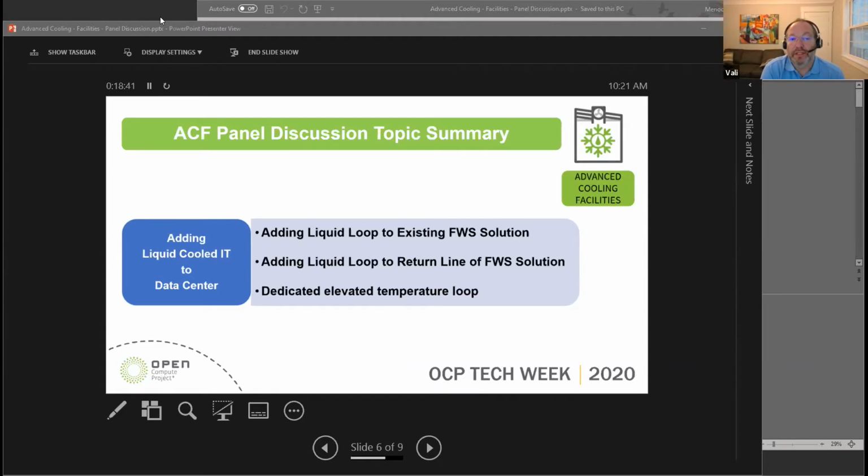There's nothing specifically magical about it, but W1, W2 are the kinds of water temperatures, facility water temperature specifically, not technical water temperatures like something that would be on the IT side of the CDU. So the facility water entering upwards of about 25 C could conceivably use chiller plants to deliver that solution.